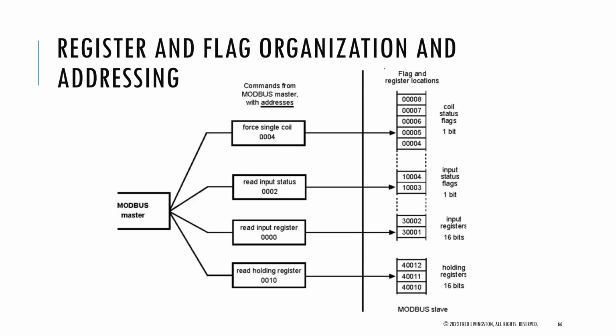One of the things here is with Modbus, we have fixed packet structures, and we could send single bits as the coil status, and we could send 16 bits as holding registers, but we can only send either one or 16 bits. In MQTT, we can send JSON messages, we can have more advanced structures there, and we can define how that payload looks and the size of that payload of the system.